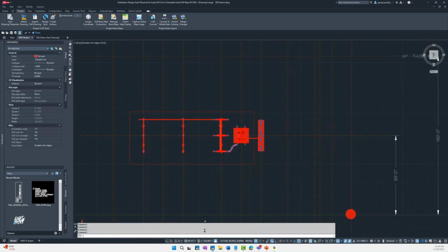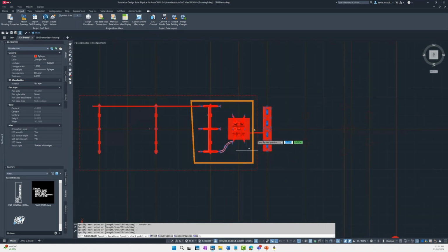First, we're going to establish a boundary. So we're going to use the AUD boundary command, and we're going to draw a boundary around our particular site where we're working. So let's say this is a larger substation, and we have been assigned as the design engineer to work on this small particular section of the substation. We're going to do some work within here, but we don't want to work in the main 3D project file. We want to work off to the side, but also send updates in real time. That's where this AUDEXTRACT command comes in perfectly.